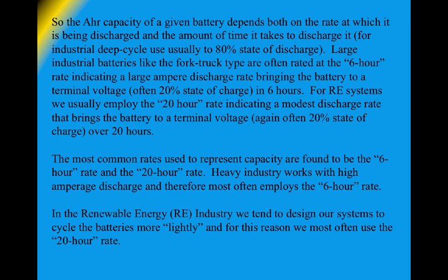Many of the batteries we use in static PV system storage, renewable energy system storage, are industrial deep cycle batteries that were developed for other purposes like traction batteries and forklift trucks. And these batteries are expected to provide a great deal of power during the day and then be charged up rapidly overnight.